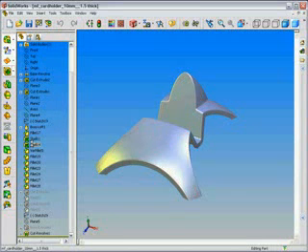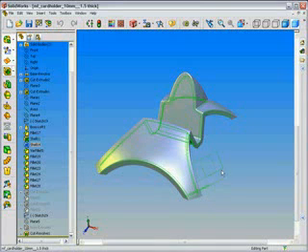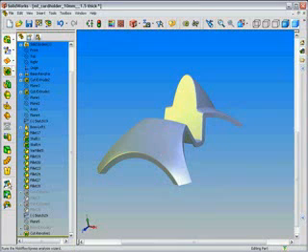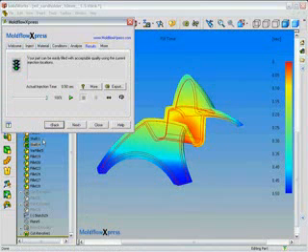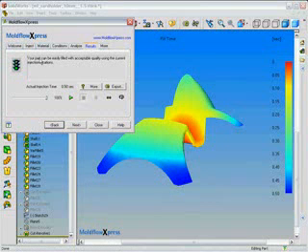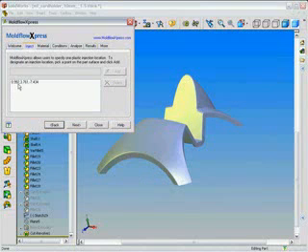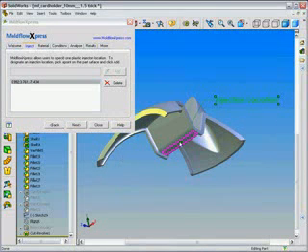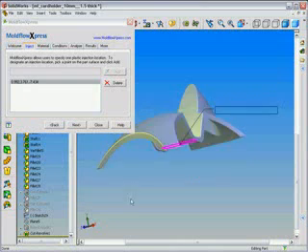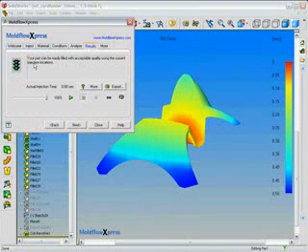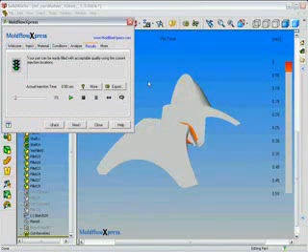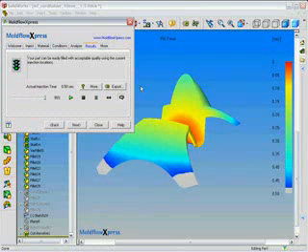You see in this variation of the model, we have a wall thickness of 1.5 millimeters, so we've actually thickened the material. Now we've also, as we launched the MoldFlowXpress wizard, changed the injection location to more central to the part. So we took some of the feedback provided by the wizard and made those changes. Now, we've gone ahead and run the analysis in advance, but you see now, based on those changes, this part will fill with our given temperature and material and geometry.